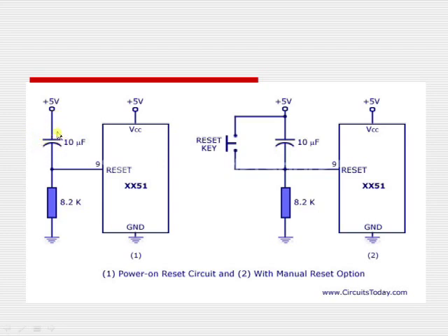So as soon as this capacitor gets completely charged to VCC, then it will not allow any other supply to cross this capacitor. Therefore this reset is logically connected to ground, which is nothing but a 0 applied over here. In case of digital, logic 1 is nothing but the supply voltage and logic 0 is nothing but the ground voltage. And we have to select this capacitor as well as the resistor values in such a way to get only the time duration of 2 machine cycles. So that is why this particular circuit is called as power on reset.